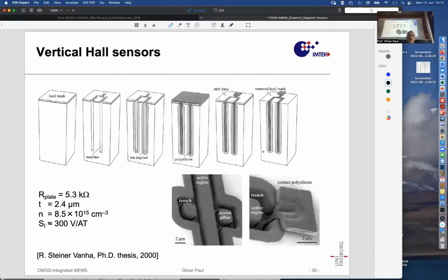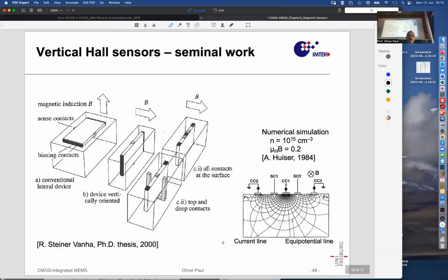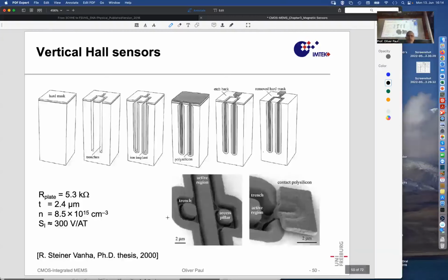And then on the other side, you have a trench that is realized the same way, by some rectangular surrounding trench etch, which defines a nice plate-like structure that can be used for letting current flow, and that can be used for letting the Lorentz force act when there is a magnetic field available.